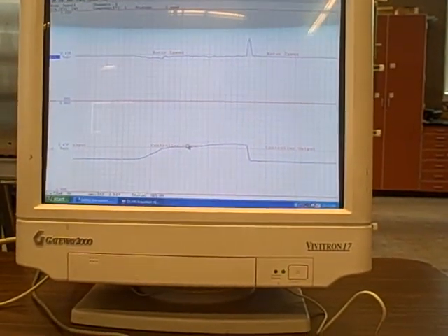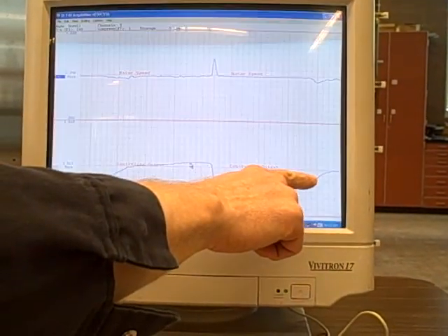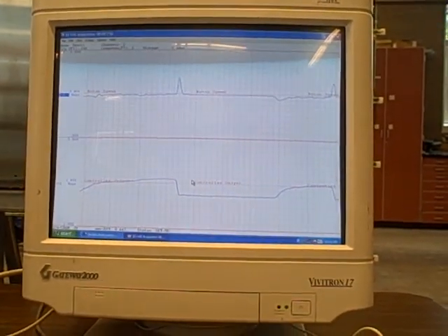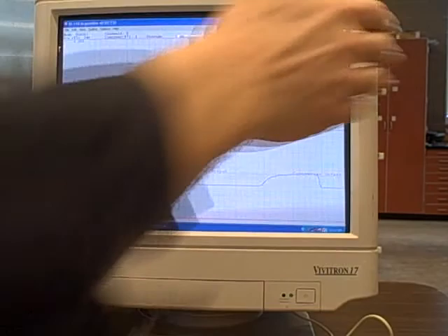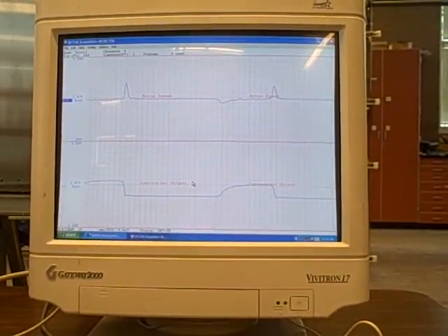Once again, I'll slow the motor shaft down with my finger. We see the motor speed drop a bit, but very quickly correct, aggressively correct, because of that integral action. When I let go, I get a bit of an overshoot, but there's no persistent oscillation like we have in proportional control. This is much better control behavior than what we had before.